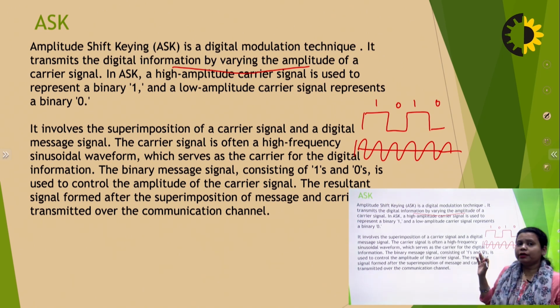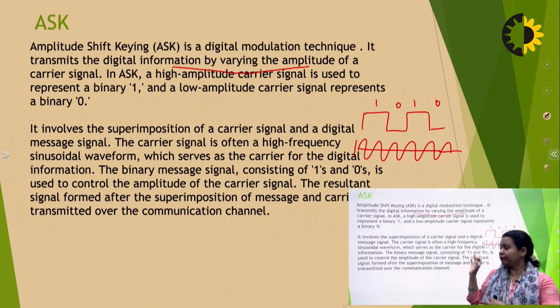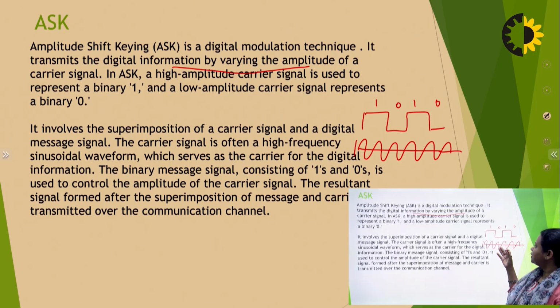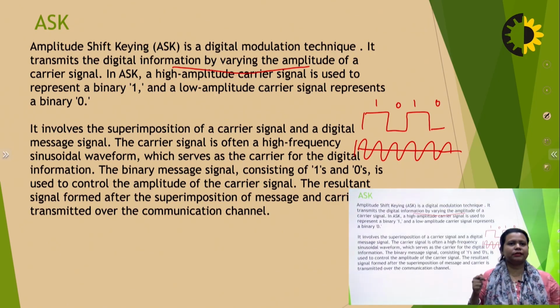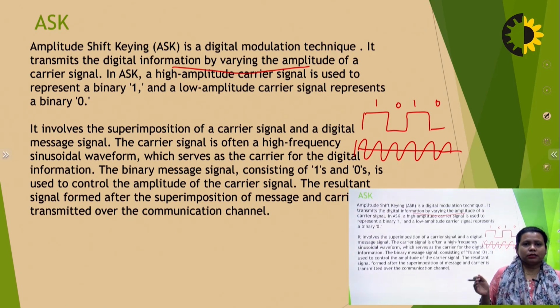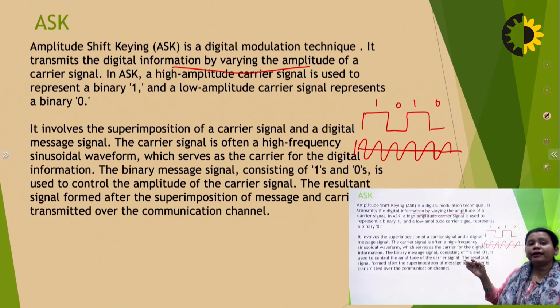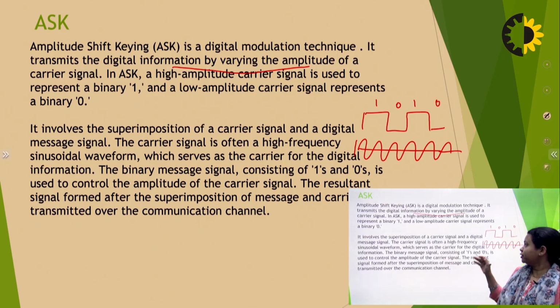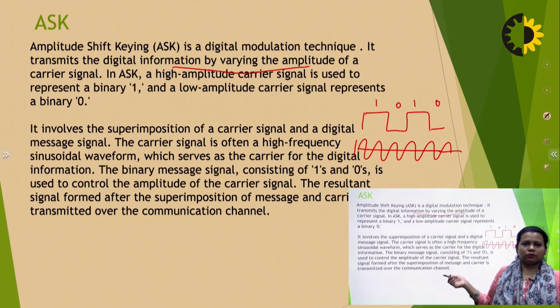One thing more: it can be asked whether there is any technique which converts a digital signal to an analog signal. Yes, although we have digital to analog converters, these modulation techniques are also such techniques, because here we are using a digital signal, and after the modulation, this digital signal is converted into an analog signal.